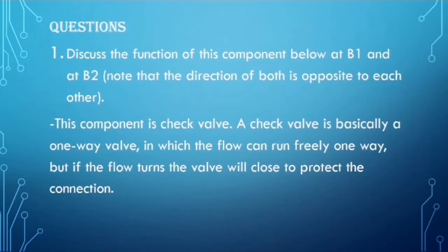Okay, for the questions, discuss the function of this component below at B1 and at B2. Note that the direction of both is opposite to each other. This component is check valve. A check valve is basically a one-way valve in which the flow can run freely one way, but if the flow turns, the valve will close to protect the connection.